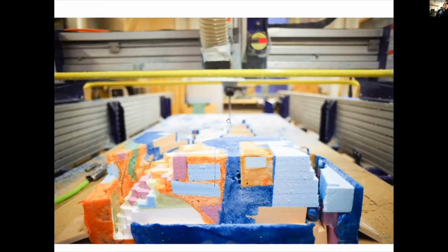We cut the parts out digitally. So there is a strong bifurcation in the waste streams of fabrication processes that are either subtractive or additive. Sometimes those meanings are blended or blurred a little bit, but typically when we say subtractive, it means sculpting or cutting away. So that would be the process of cutting wood, sanding something. The CNC mill that you see here is obviously one of them. Maybe not so intuitively, the laser cutter is also subtractive because it's removing material, albeit efficiently. But the CNC is one of the most subtractive of them all, and potentially one of the most wasteful.